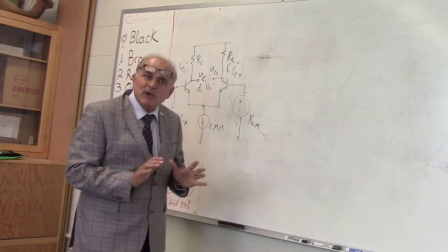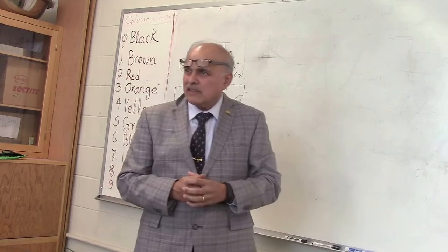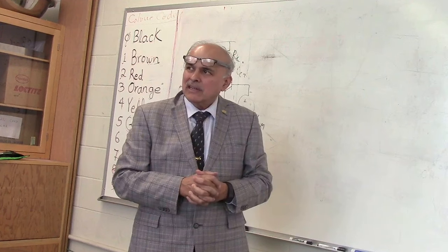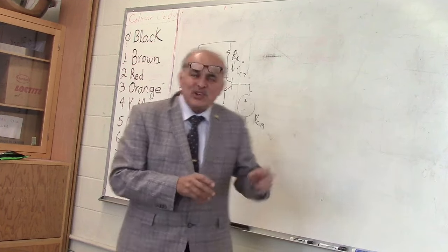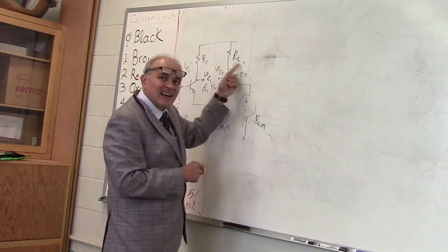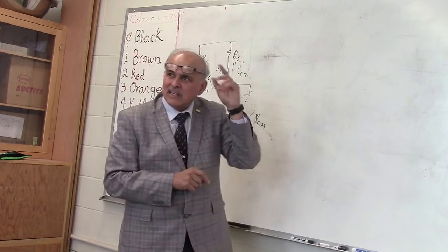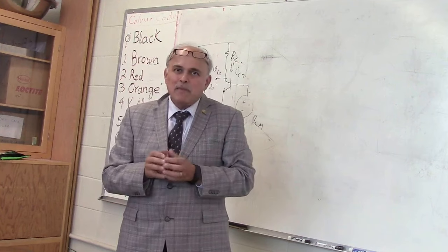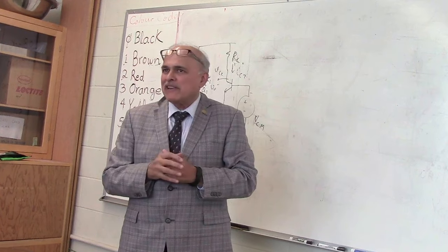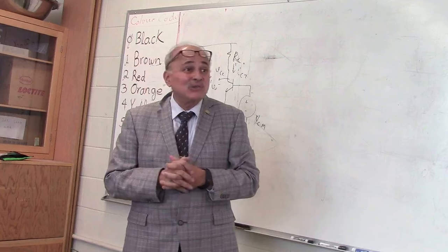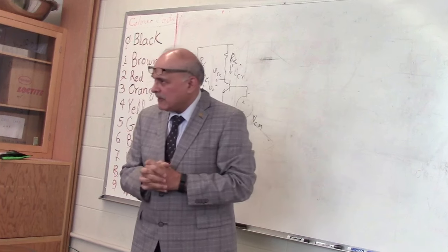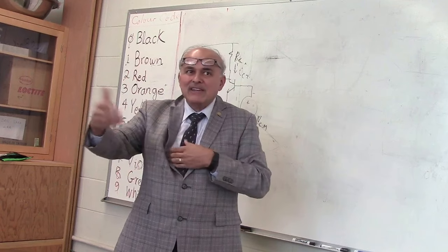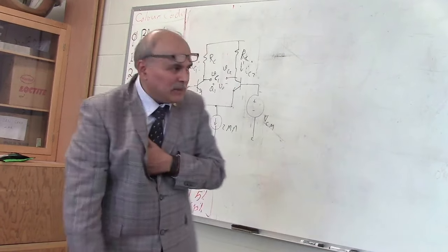And so the common mode gain will only change if the resistances are different. Now in this lab, they've asked you to calculate the common mode gain, but they haven't told you how much uncertainty to expect in RC. So if you want a theoretical answer for this, you'll have to actually measure the RCs. But for this lab, I'm not expecting you to give a theoretical answer. We're just asking you to measure the common mode gain and report it. But if you want to do a little bit more for bonus marks, you can actually calculate it. We'll see how to calculate it in a minute.